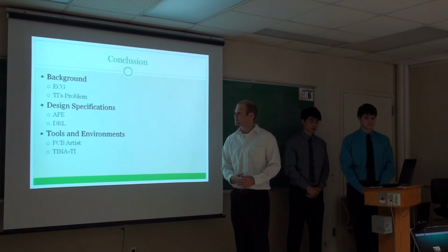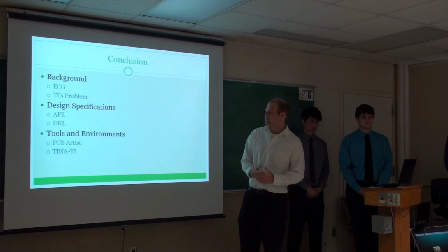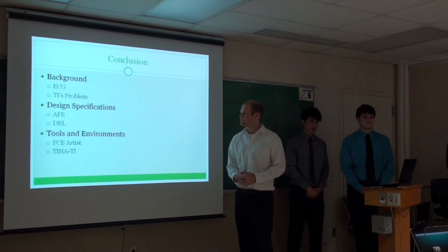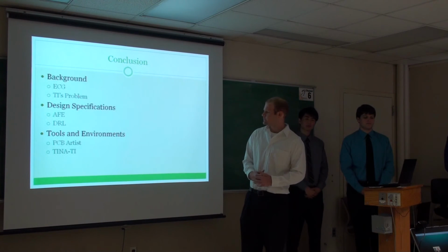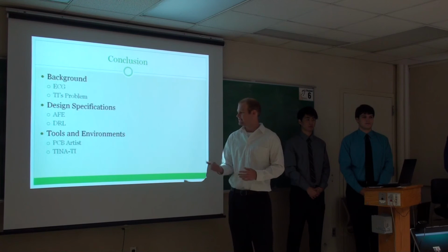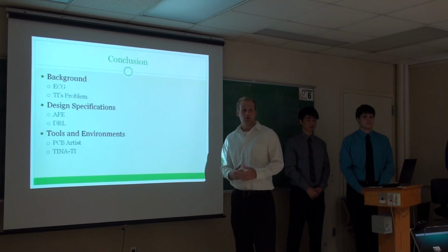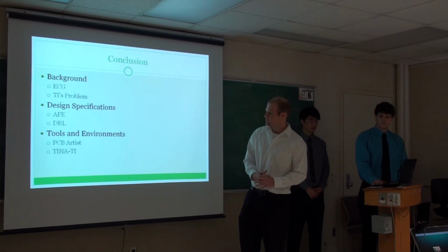So how we can take our input signals and eventually read them on our scope, and how we're going to take the driven right leg approach to our circuit, and also use other noise cancellation techniques for optimal signal response. Tools and environments, we are using PCB Artist for design, like we showed you, and TINA-TI for simulation. Both were requested from Texas Instruments, so that's what we have been using and will continue to use.